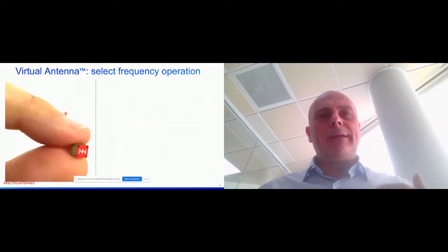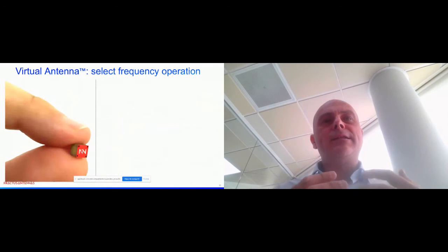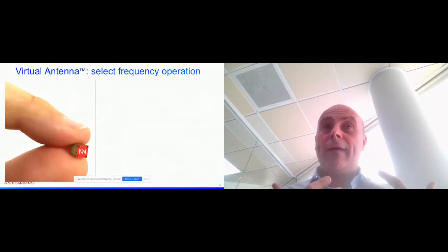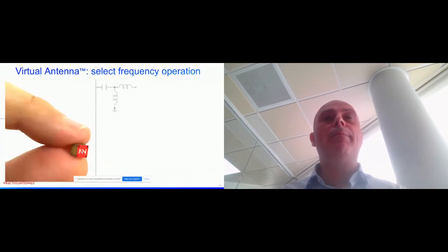As we said before, antenna booster, you can see here how small they are. The frequency is not given by the antenna booster. It's something that you as a designer can fully choose. And how can you do that? By the addition of a very simple matching network.